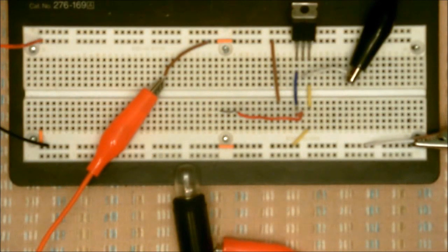So if you're going to be working and testing with this MOSFET, be sure you got an anti-static wrist strap connected to a ground to help dissipate any kind of static charge you may have. Especially if you're going to replace these. If after this test you find you have a faulty MOSFET, when you install the new one, you still need to take the precautions to avoid static electrical buildup.